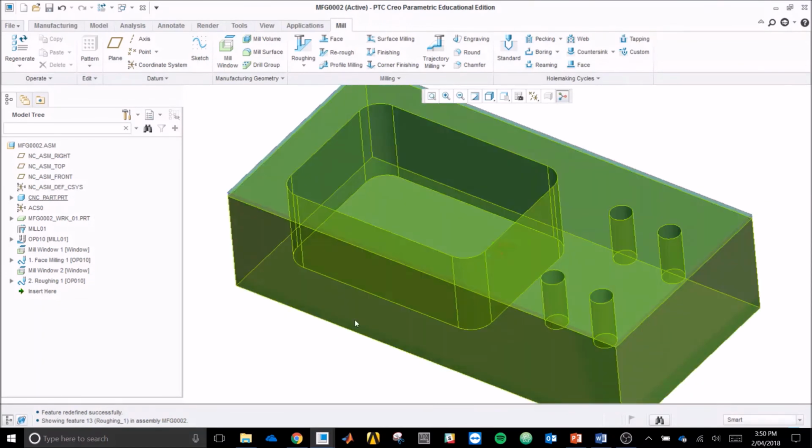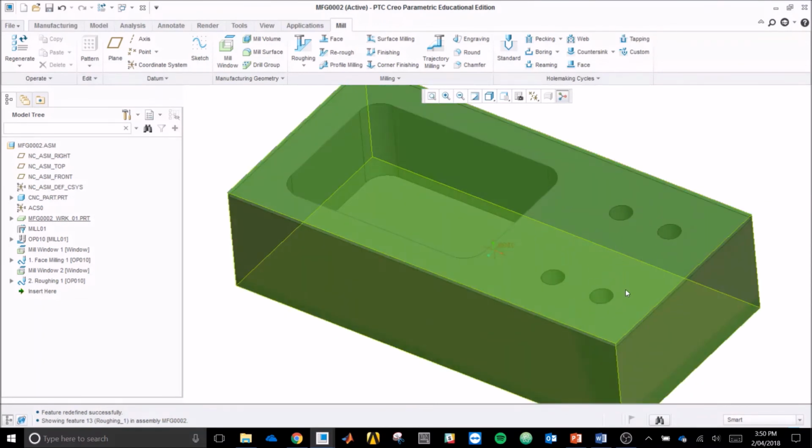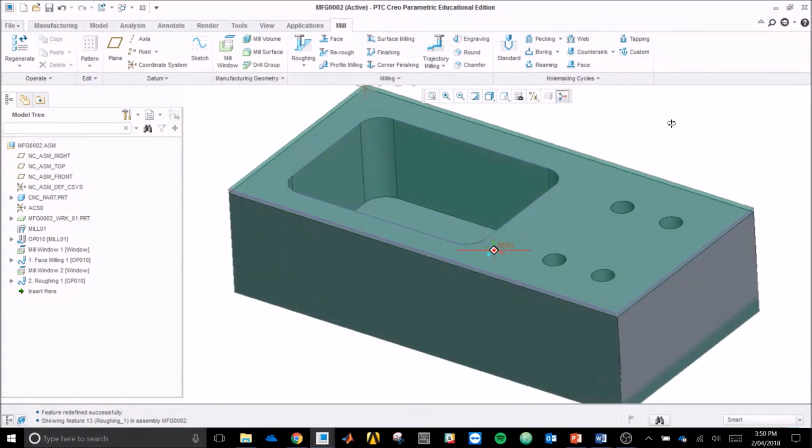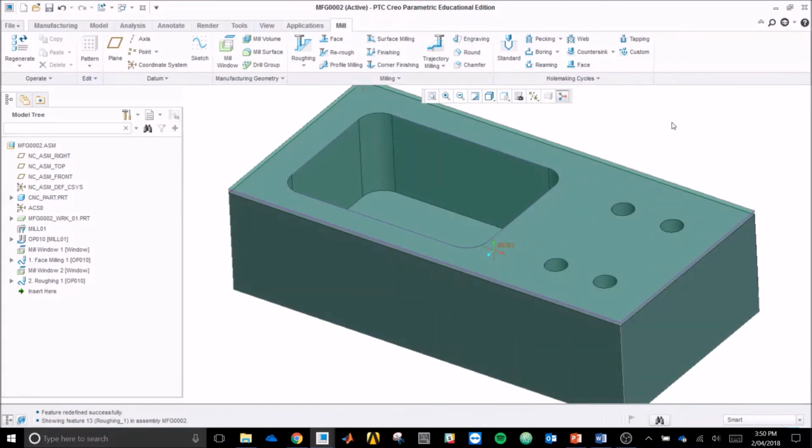Okay, the final operation is going to be drilling out these holes. So they've been face milled, so now we can drill those out. So we're going to use PECK drilling. As these holes are blind, it's impossible to drill these holes straight in one operation. In reality, the drill bit's going to have to drill down a few millimeters, remove that to release any swarf or cuttings, and it represents a pecking motion. So PECK drilling is often what it's called.